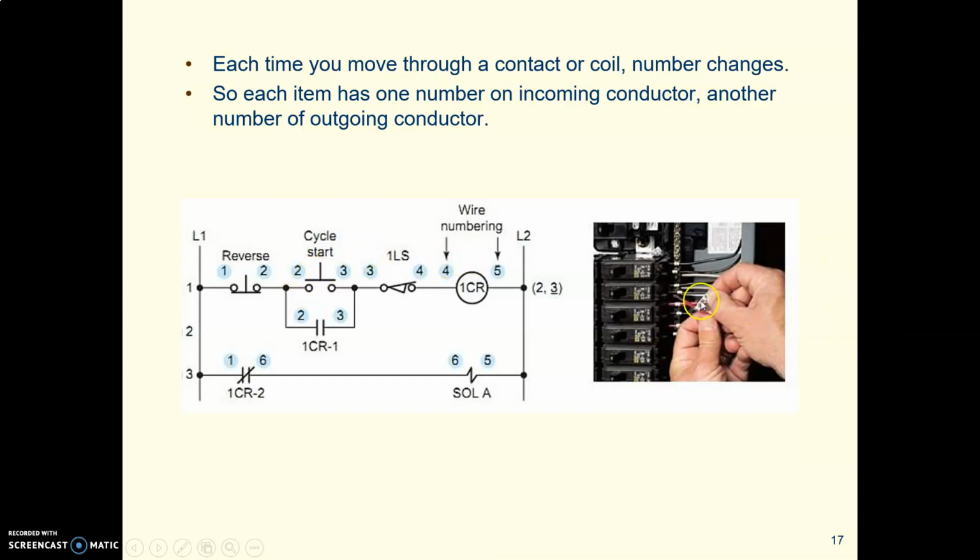Meanwhile, our electrician gets these purchased wire number labels. Our electrician puts that same number on that wire using your ladder diagram and your numbers. The actual wires match those numbers. So now, if somebody has to come along later and troubleshoot, they can follow exactly what wire is going where.